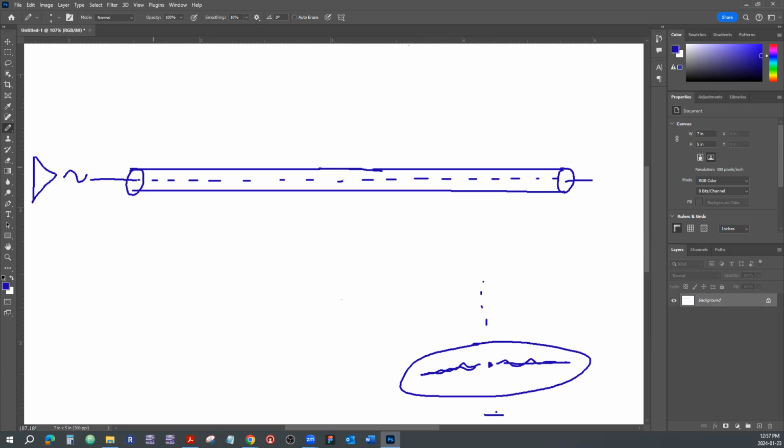Well, same thing with the wire, with this coaxial cable. The amplifier introduces a wave and just shoots it down right here, and the wave travels on its own. And it just gets smaller and smaller and smaller as the cable gets longer. So that's how we can say how far a certain cable can carry the wave, right? So obviously, thicker cables with thicker gauge wiring can carry the signal further because they'll have less physical resistance.